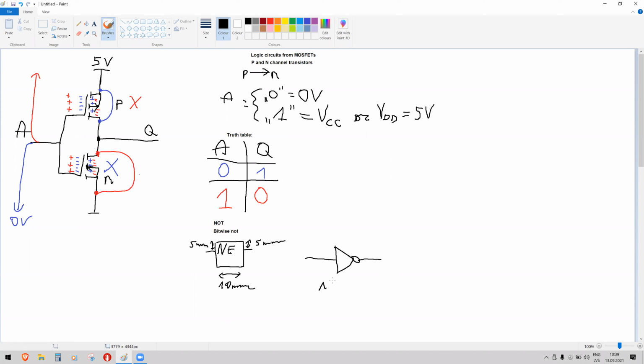So the triangle basically means the repeater of the signal or a driver, and the ball at the end means the opposite, the inversion. So for other logical elements, if we draw an element and put a small ball at the end, it means invert whatever was coming in. So this is the first logic circuit, and you did pretty well determining the output.